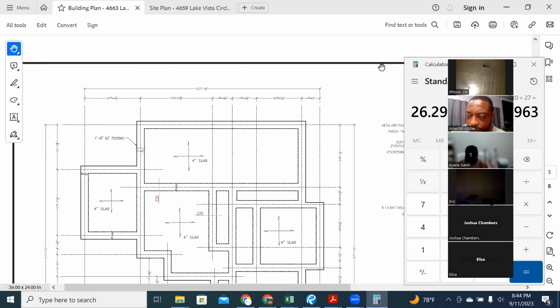Is it always like that, or is that just a coincidence? Like, is it always the slabs equal to the exterior? Not at all. Yeah, it's not always that way because you don't always have to have a 20-inch width and a 24-inch deep footing either. Sometimes it's 18 inches by 18 inches. The smallest I've seen is 12 inches wide and 12 inches deep. We've actually passed some inspections like that. It's all based on what the plans call for because the engineer is the one that has to back it up.